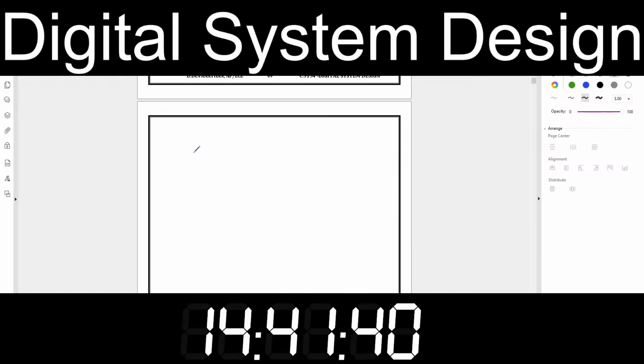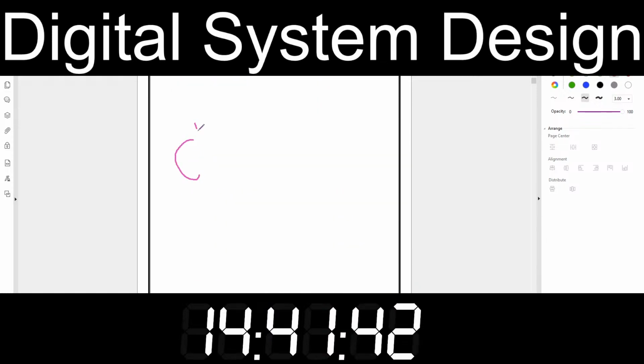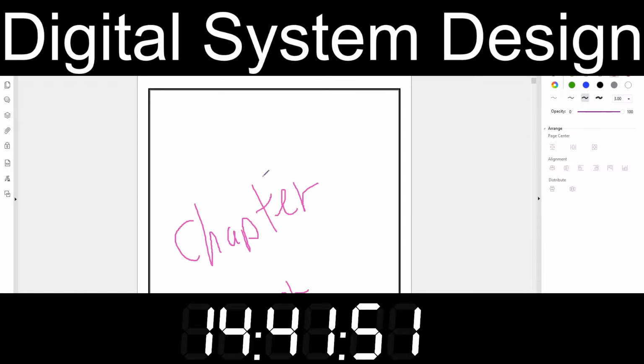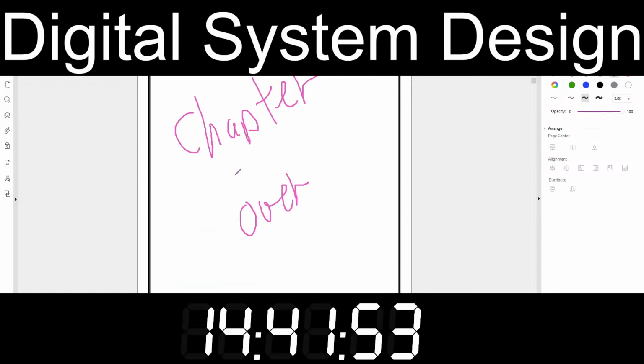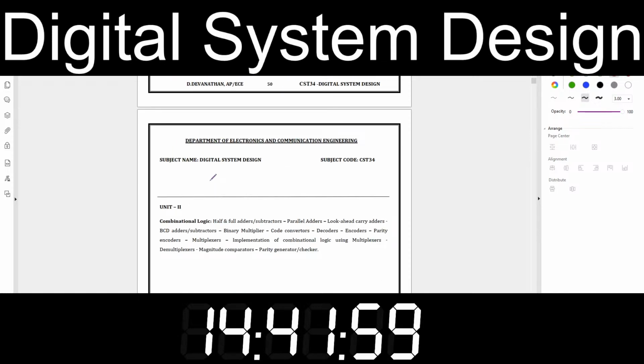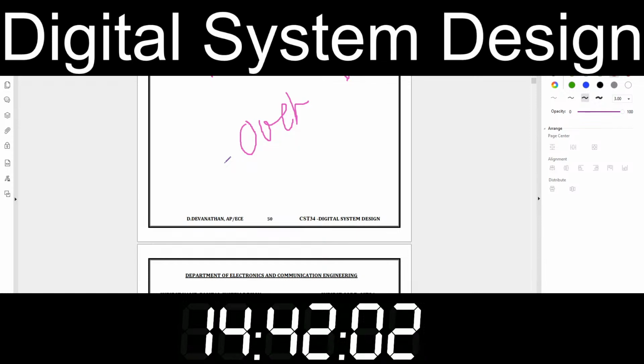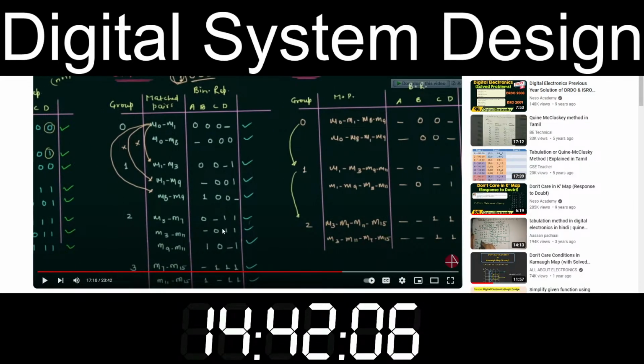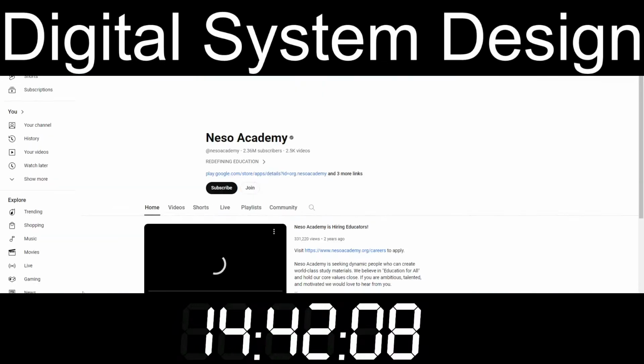In this we have B complement D, and for this we have CD. This is our prime implicants. All these three are prime implicants, and we also have to check step number 2 for any matched pair which is untick, but there is a tick in front of all the matched pairs, so there are none.